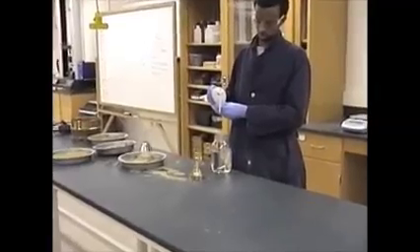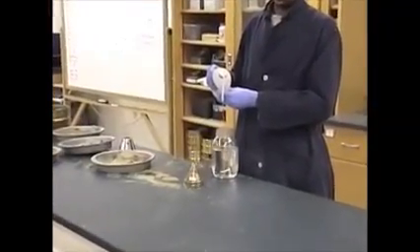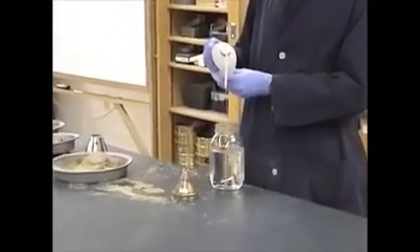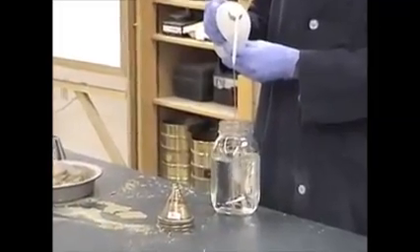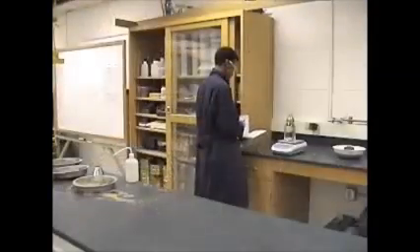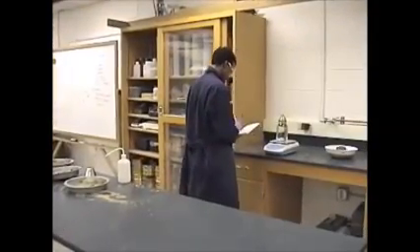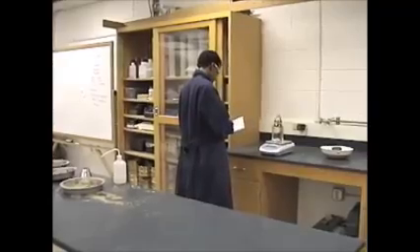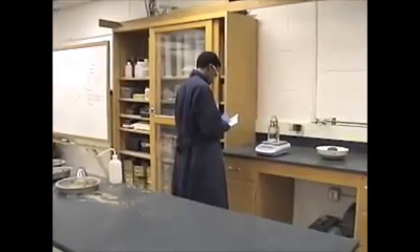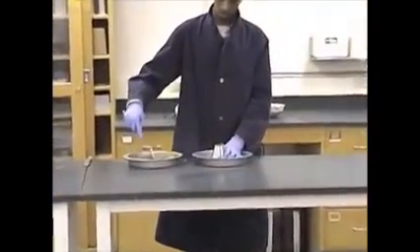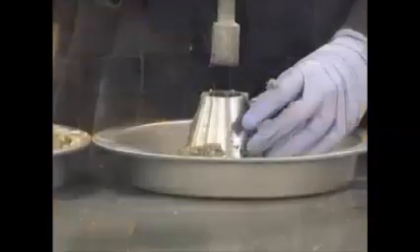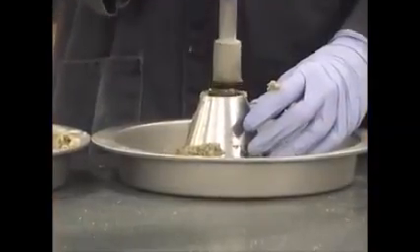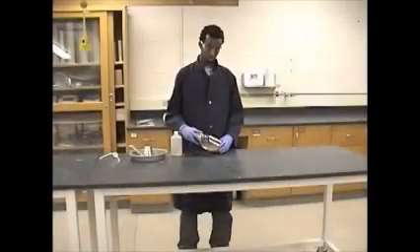We now want to fill the mason jar with just water back to the calibrated mark. Be sure that the water's temperature is 23 plus or minus 1.7 degrees Celsius. Then record this weight to the nearest 0.1 grams. Now that we've completed all the physical aspects of our tests, we can go ahead and do our calculations.